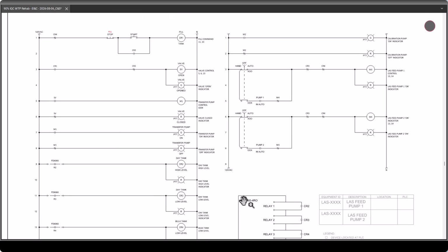Okay. Do you know the possible ways to get a low level signal? Do you mean just as far as like a digital output signal or something from a transmitter? Yeah, like we could put a pressure indicator or pressure transmitter on the bottom. We could do a level indicator from the top. I think this one has a level indicator on the bottom only. Okay. So all of those questions that I'm asking right now, that's the very first thing that a contractor or the panel shop builder is going to ask. You're telling me these things, but you didn't tell me what they are, how we're getting them, stuff like that.